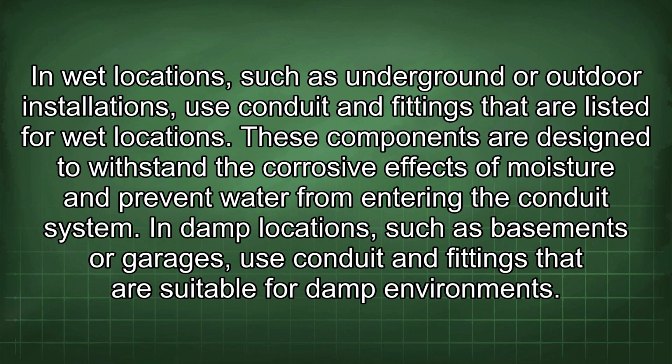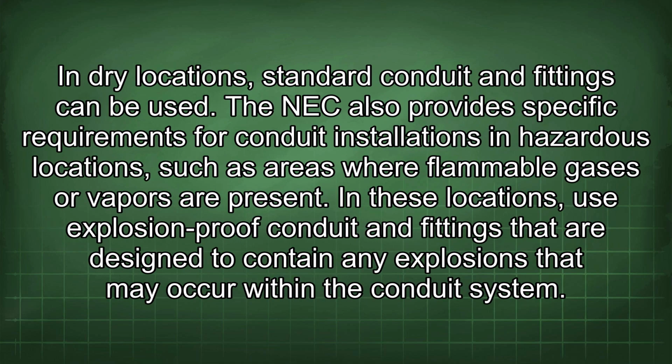In damp locations, such as basements or garages, use conduit and fittings that are suitable for damp environments. In dry locations, standard conduit and fittings can be used. The NEC also provides specific requirements for conduit installations in hazardous locations, such as areas where flammable gases or vapors are present. In these locations, use explosion-proof conduit and fittings that are designed to contain any explosions that may occur